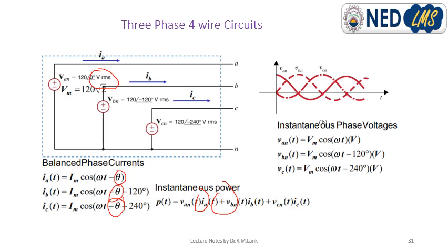It is the RMS value. We must know that the voltage values recorded by instruments, that is a multimeter or ammeter or whatsoever, are actually giving you RMS values. The 220 volts is also an RMS value, right? So RMS values of voltage and current are measured by all the instruments.